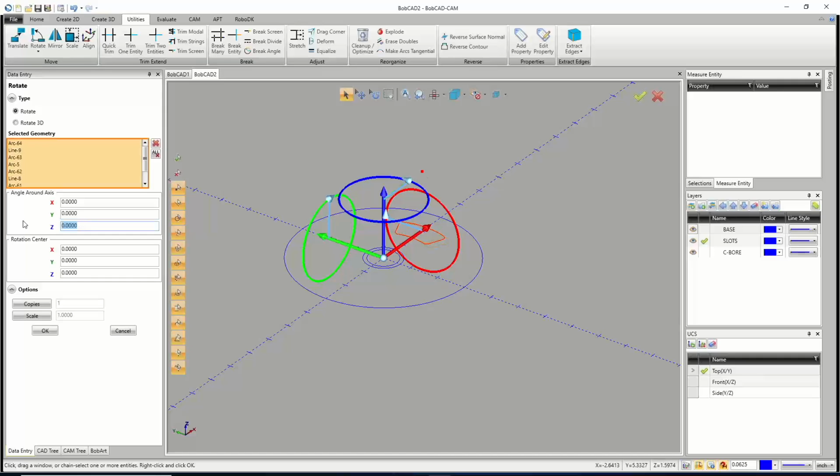And then you have to look at your angle. So again, we'll go 360 divided by 6. Now, the center point should always be in the absolute center of the geometry, but that's not where it automatically goes. If you have a piece of work, a part that you're working on, and you're working in this upper right-hand quadrant because you like all your dimensions to be in the positive quadrant, which is totally awesome. Brain doesn't work that way. Great, do it up there, but you'll have to move your rotation center point to the center of your geometry every time, which can get a little tedious.